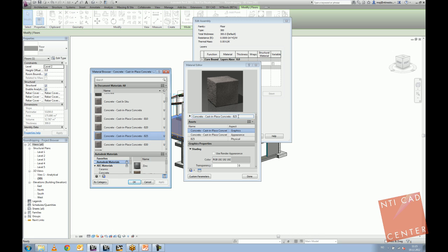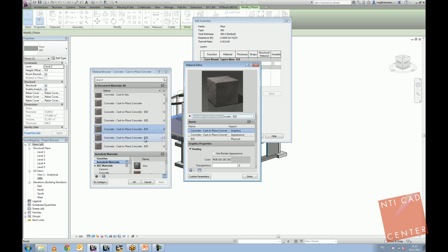First of all, the name is too long. So when you have this long name and you create this name in Revit, basically only the first part will be created. So if I will have several different strengths of the materials, for example, this one, and then something else, all of them will have in Robot one name, and basically one of those, usually the first one, physical properties will be used. So basically all of your elements will get the same material. So that's kind of a scary thing. Other scary thing, which is really scary, is actually all of the physical properties. For example, for a concrete B25, you have a concrete compression strength which is 30.